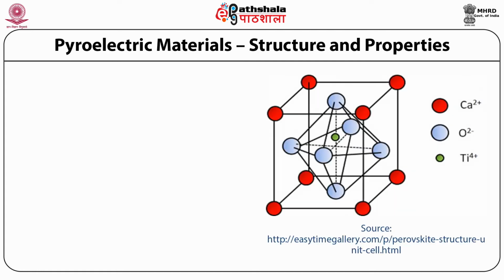Pyroelectric materials, structure and properties. Pyroelectric materials are non-centrosymmetric polar dielectrics. Most inorganic pyroelectrics have a perovskite structure. The figure shows a unit cell of perovskite, that is calcium titanate.